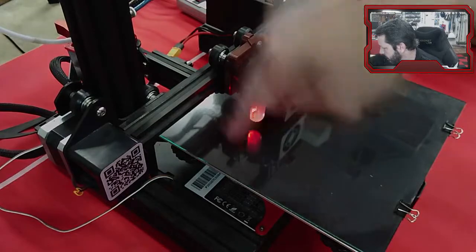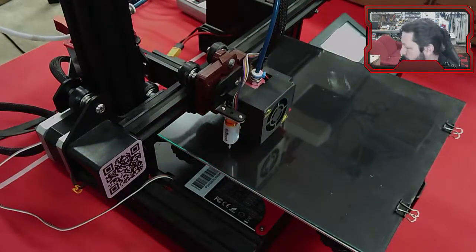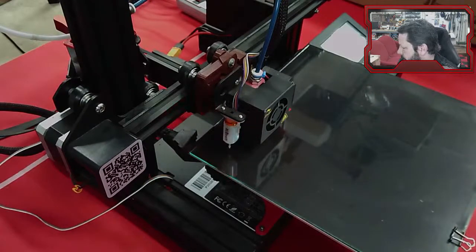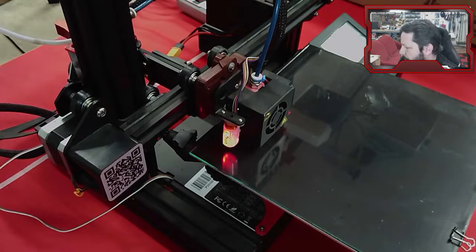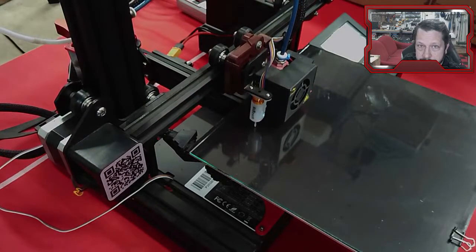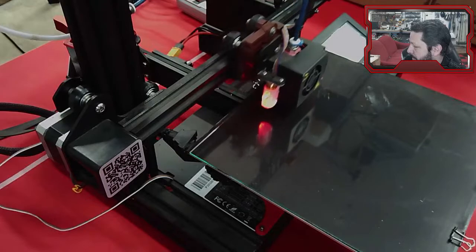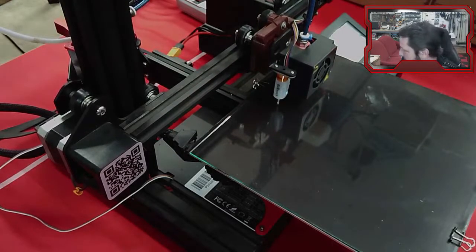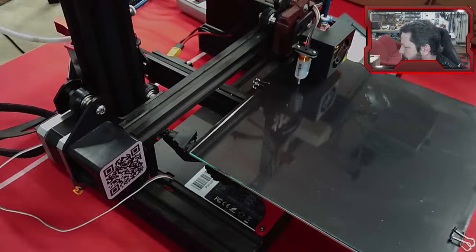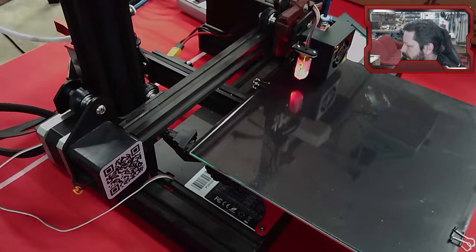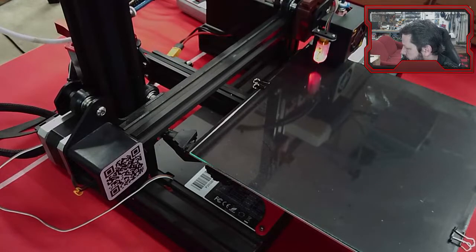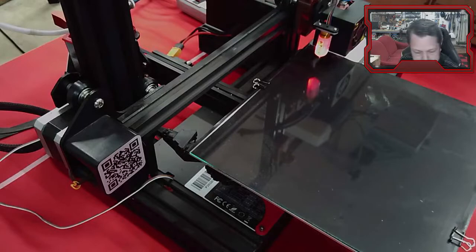So it's got one more here, and then the back row, and then it's going to start its purge, and then it'll start its printing routine. And once it starts, and we look at it a little bit so we can see what it's doing, normally you want to watch the start of it, and over time you'll be able to tell if the print is going to succeed or if it's going to have problems. This printer, with all the stuff that's on it, is generally set up to where it's going to be fine. I could just leave it alone and let it do its thing, but this is the first time it's printed today, so I'm going to watch it and make sure it starts right.